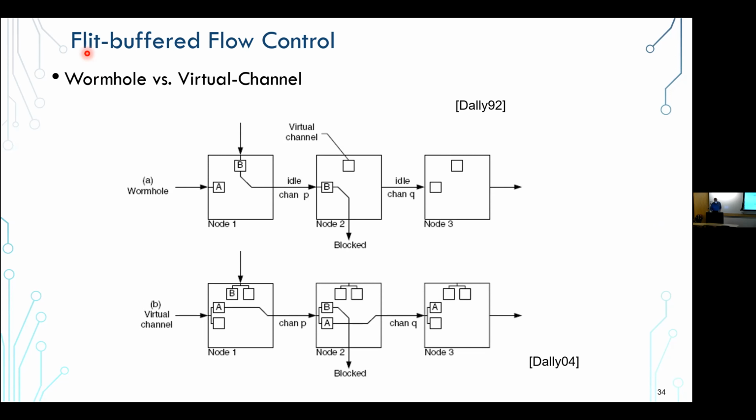And so the next better thing to do is to chunk the packet into flits and let those mingle through all the shared resources, through the buffers, through the channels, so that you can let others pass through if you are blocked somewhere down the line, right? And so we talked about wormhole routing, which lets you send the first flit even though the rest gets blocked.